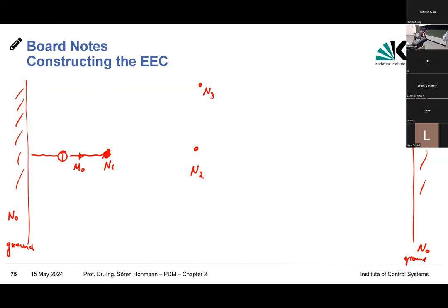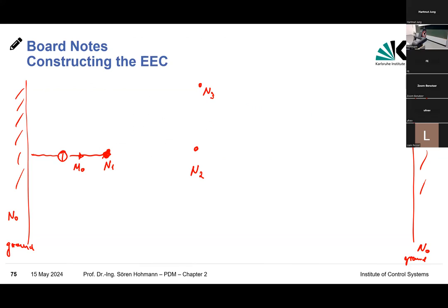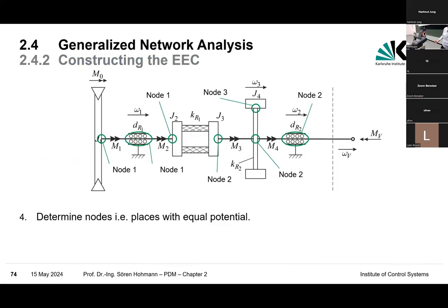And then next, let's have a look at the first bearing. So back and forth between these two slides, sorry for that. Here the first bearing somehow is modeled by means of friction. Friction is what in equivalent circuit notation? It's a question, yes? Exactly, the resistor. So, and now the question, if the node 1 is velocity 1, so back here, where does the bearing have a second reference point or a second connection to?